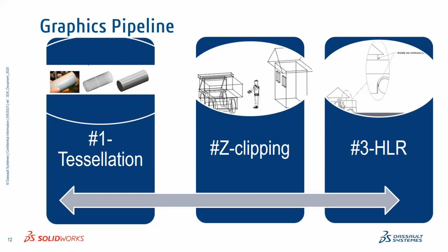Third is the biggest, or you can say the most graphics time-taking, which is HLR. HLR means, in the same way, the same example. Here I took the model in between these two models, and I want to see in one view the hidden lines or hidden things, what exactly is behind it.